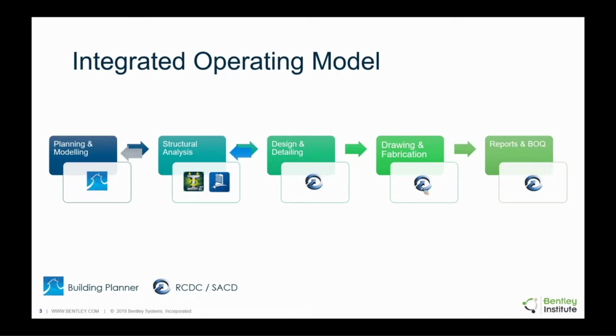And the output of the building planner is a STAAD profile. So it actually creates an analysis input into STAAD. Go into STAAD, do your analysis, and post that we have the RCDC or the STAAD Advanced Concrete Design, which takes over and takes you through the rest of the process. So this solution directly interacts with STAAD, takes all the analysis output from there, and then takes you through an interactive design and detailing exercise so you can control the entire process.